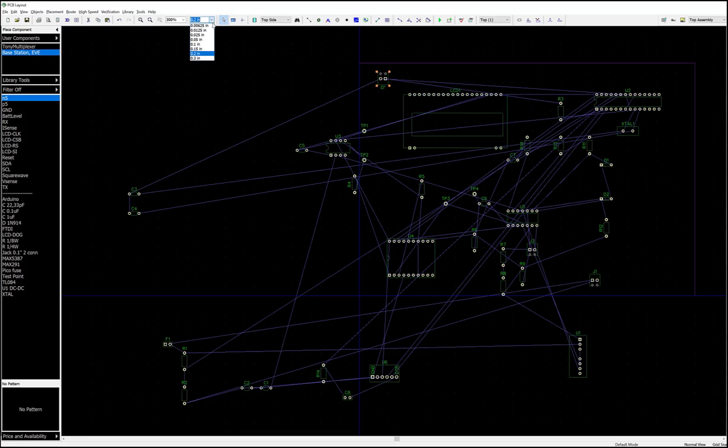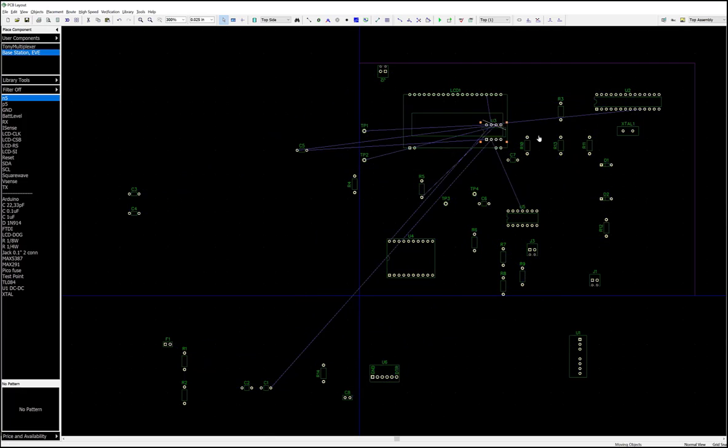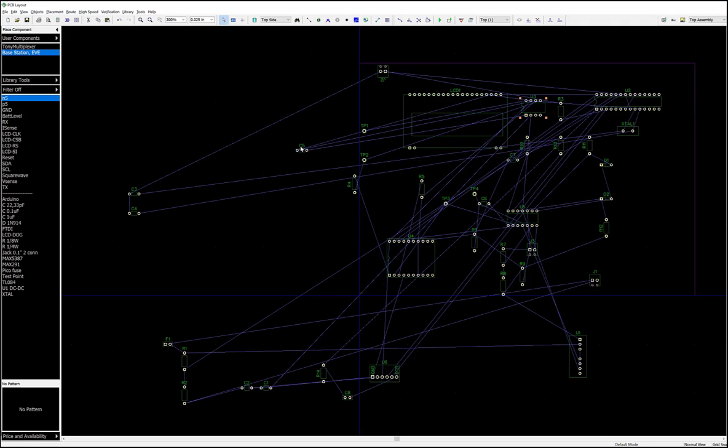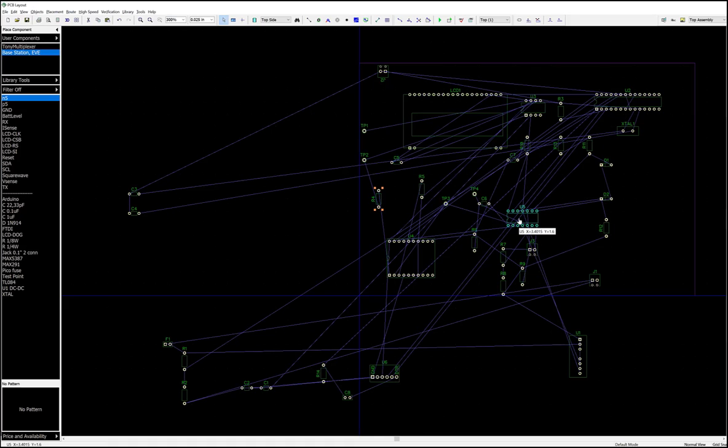And now that I've got my board placed, I'm going to put my spacing much finer so I can bring it much closer to the side of the board. As you're placing these components, you obviously can't place them on top of each other. And maybe it's clear now why you have these outlines in green to show you the size of the components. You should be able to see for R4 that this is just a bad connection. It should be derotated R4 to make the wires cleaner.